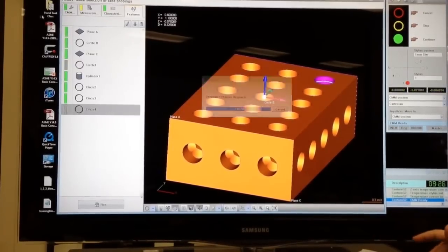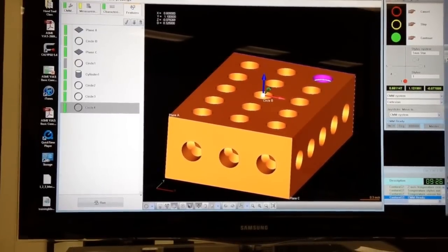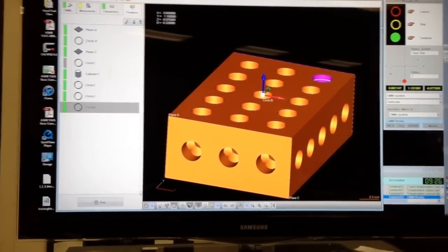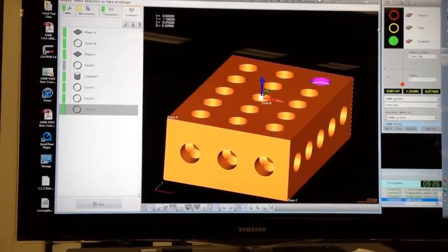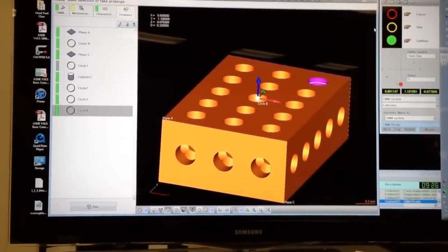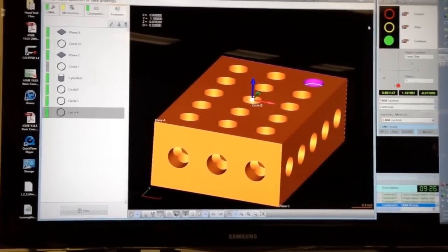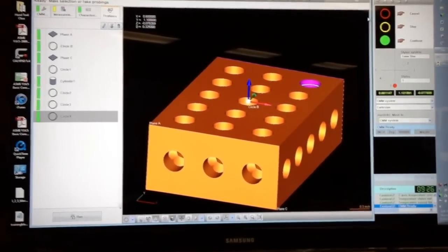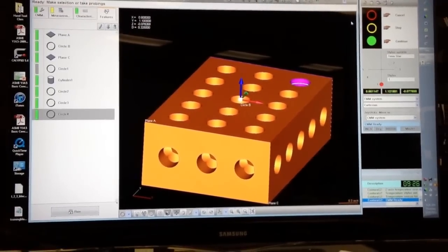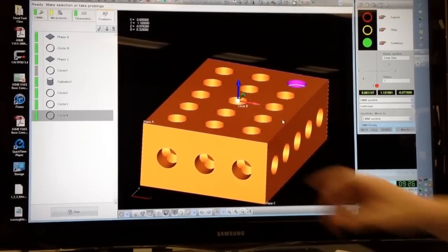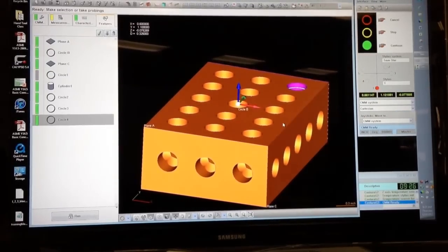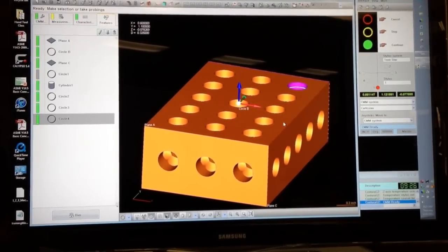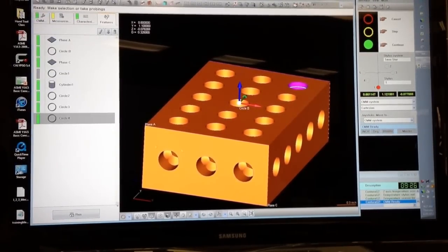I press F9, and now we've test ran circle 4 as well. Next, we'll be doing an angle between features, tolerancing two lines constructed from the three holes along the left side and the three holes that run diagonally across the block. By the way, the circle names are given in the lesson, but if you rename your circles here to circle B, then your numbers in the lesson will not match. Okay, so don't get caught up on that detail.